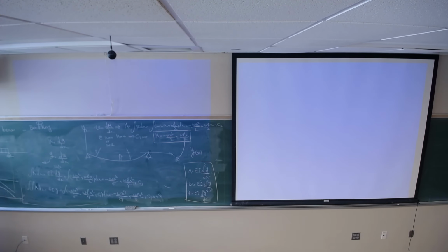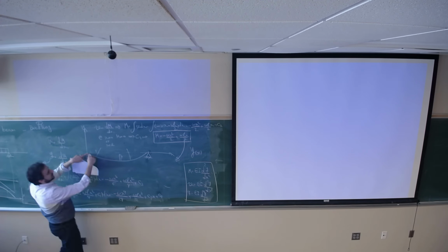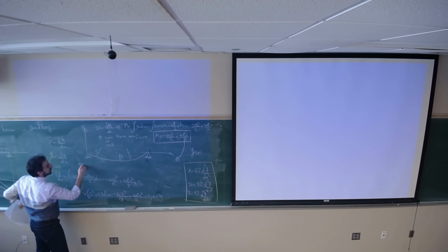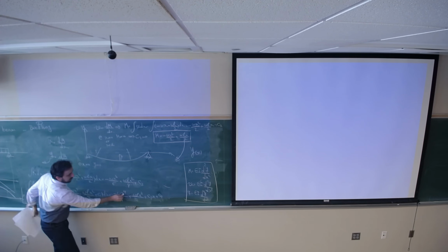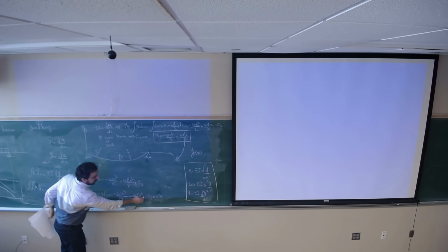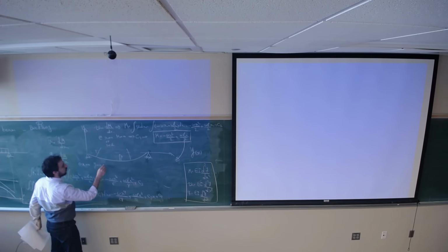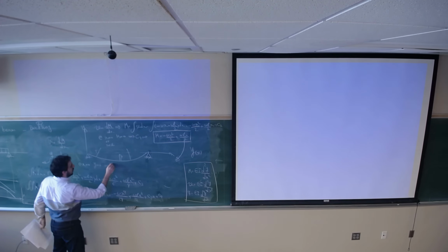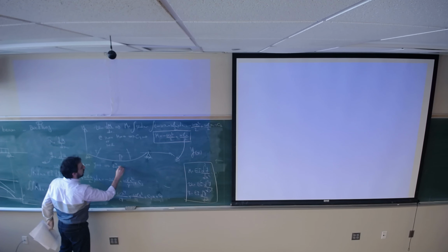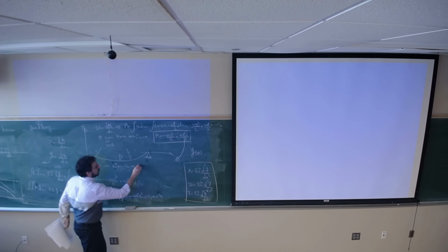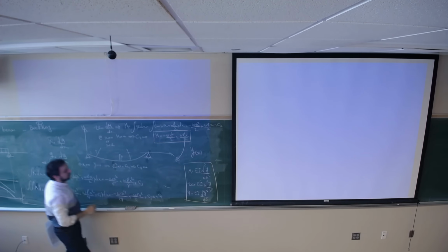If you look at the beam, at the starting point x equals 0, y is 0. We don't have any deflection. Just plug in x equals 0. This term is gone, this term is gone, this term is gone. So C4 is going to be 0, to satisfy the first boundary condition.